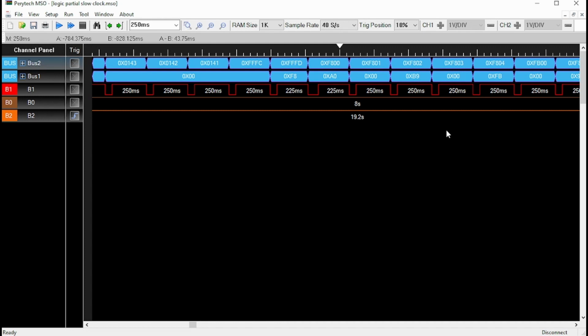Everything's working just right. One thing to bear in mind is we've got the clock being used here, and this clock is our slow clock. It's not a linear clock, as we can see here. So it's only got a small area here where it goes low and then it's high for a lot longer. That's just how that circuit was generated. So just whatever specific capacitors and resistors we're using will create that.